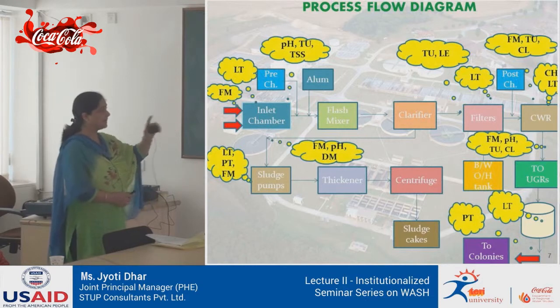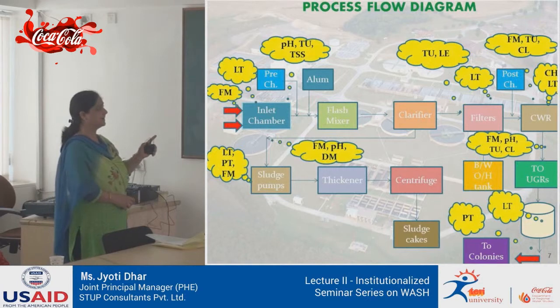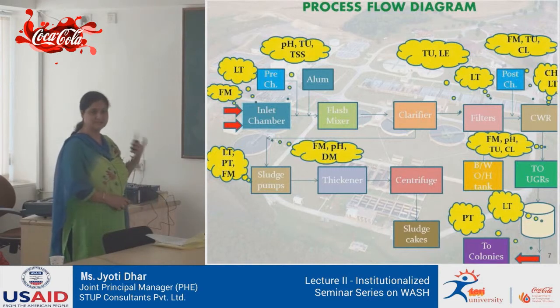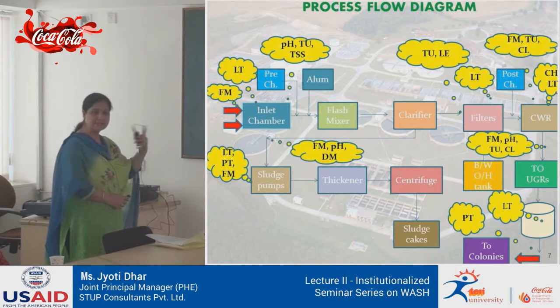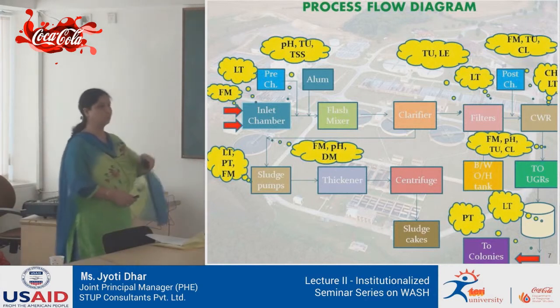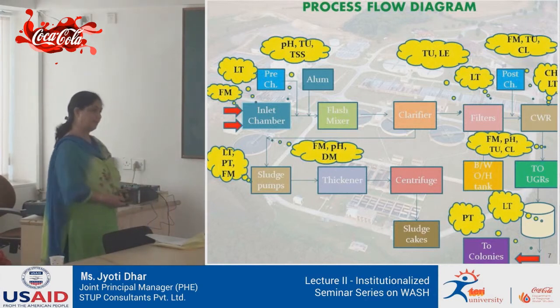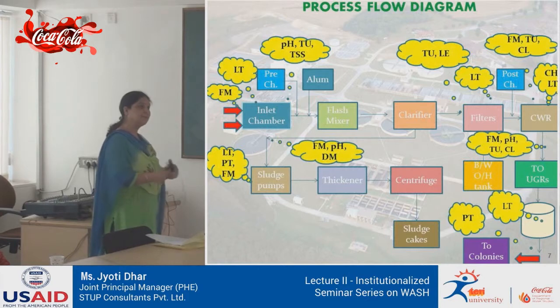Similarly, pumps which are scattered over the area of the water treatment plant are controlled with the help of the level transmitters. Once your level is low, the pumps will start in order to fill the reservoirs, and once a high level is detected, the pumps will stop, so that the water doesn't overflow from the tanks. From the SCADA system you instruct these pumps? Yes. It's actually a programmed thing, and you have various software for that.